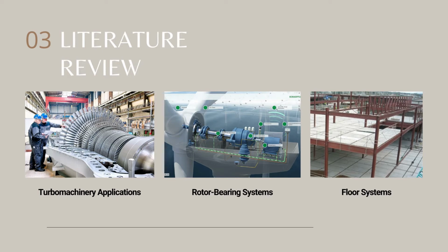Rotor bearing systems. Analysis of dynamic response of rotors is crucial, especially at high speed. Glasgow and Nelson 1980 applied the method of CMS to the problem of dynamics of rotor bearing systems, in particular whirl mode and stability analysis.